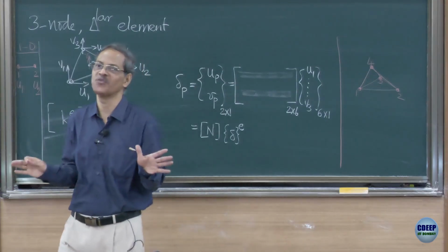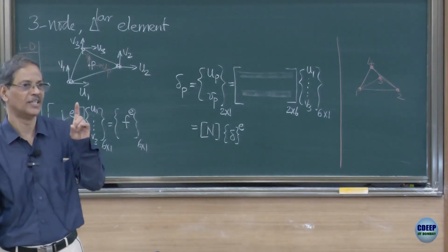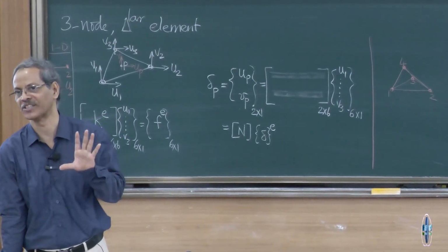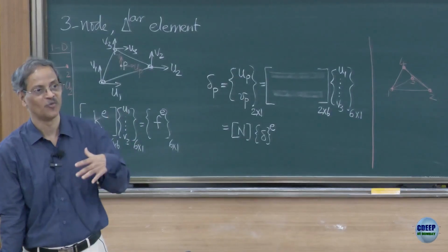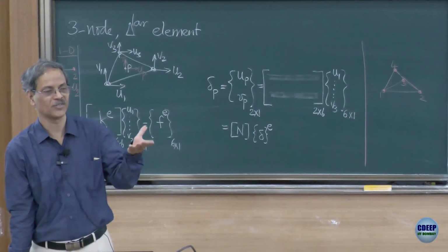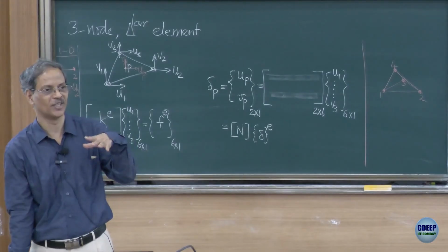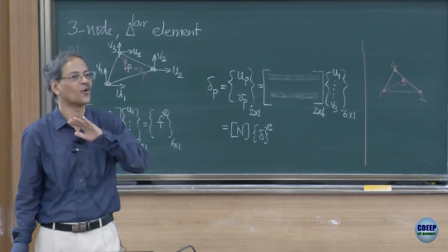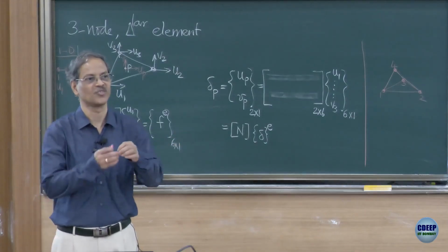In each direction x, y, z, because you have only 2 nodes, you would still have only a linear shape function, interpolation function. The first derivative, whether it is heat flux dT by dx kind of term or strains dou u by dou x kind of term, will be constant along x, y, z.